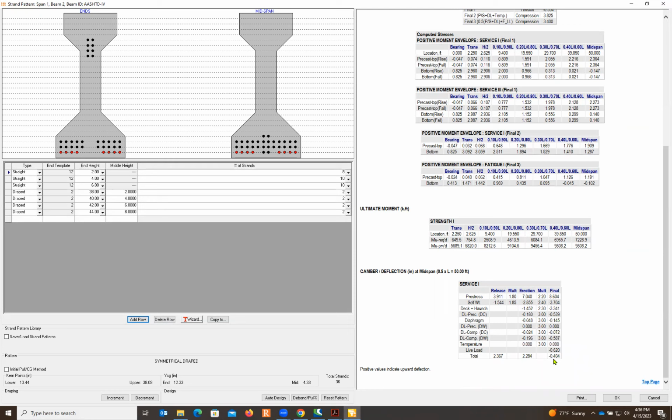For this scenario, you do have an additional way to improve that. One thing is you can put in the prestressing strand contribution in order to improve the moment of inertia, or you can add more strands.